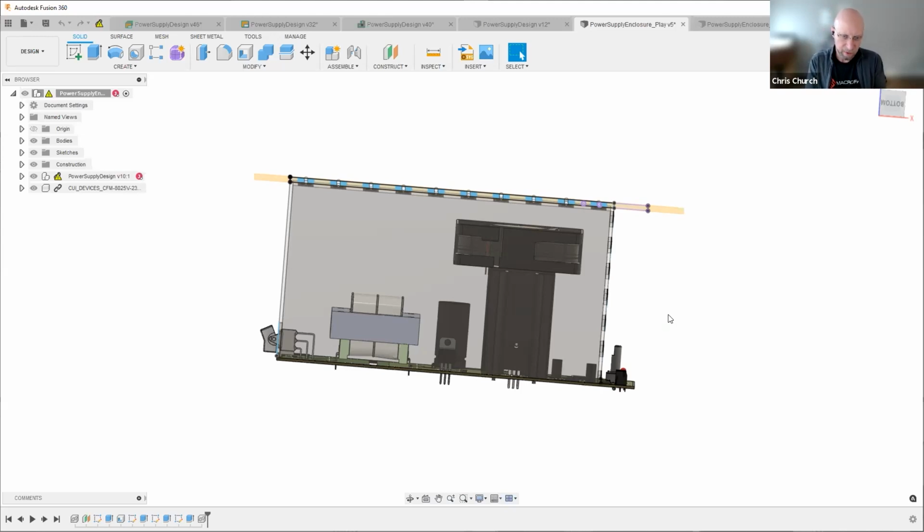One of the questions our team would have for you is, what is the look and feel you're going for here? Are you going for a real clean outside look? Do you want to minimize any possible user interference? If so, we'd want those screws to come up from the bottom of the fan into the enclosure itself. And so we would work with the enclosure manufacturer to add threaded inserts at those locations. They can either do press fit, or brazed on.